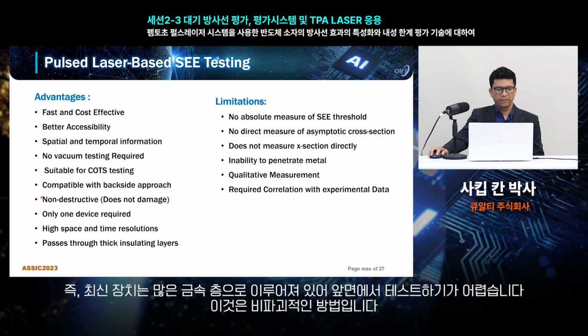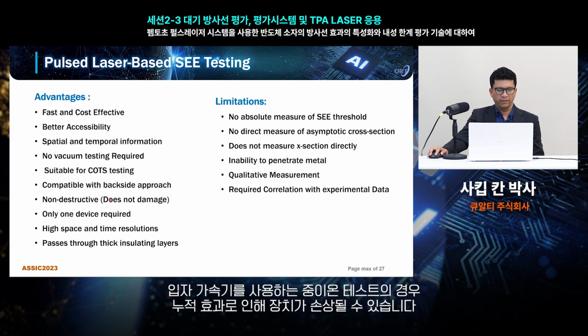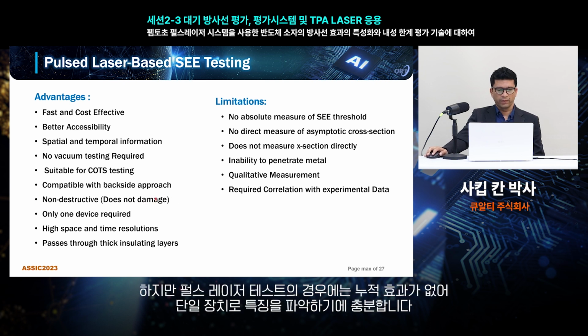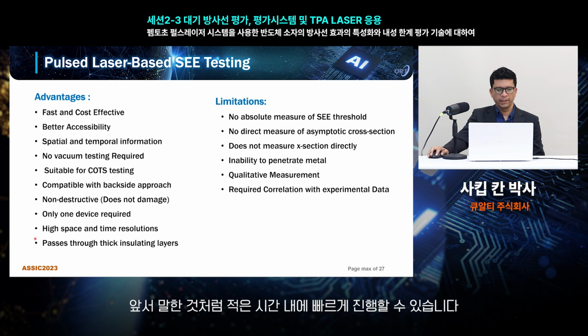It is a non-destructive method. In the case of heavy ion testing, with a particle accelerator, the device may get damaged due to the cumulative effect. But for the pulse laser testing, there's no cumulative effect, so a single device is enough for the characterization. As I said, it is high speed and high time resolution.